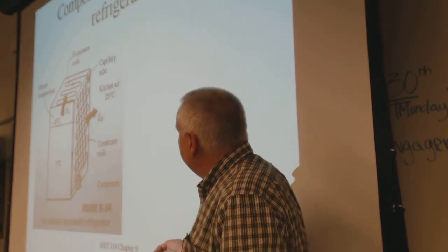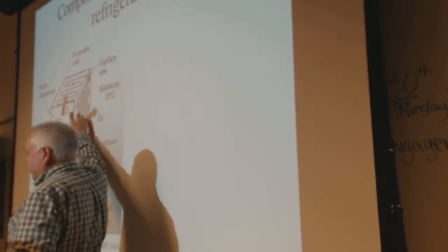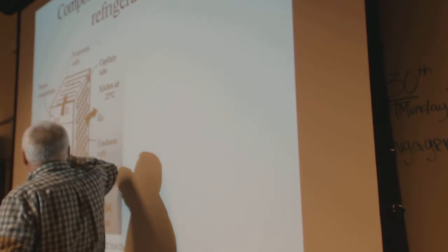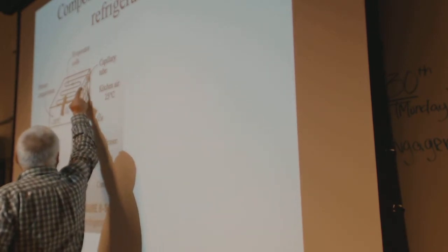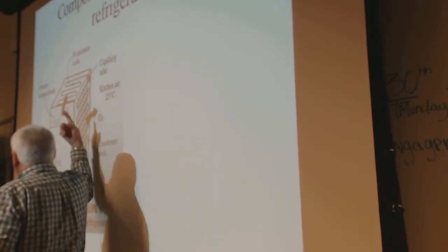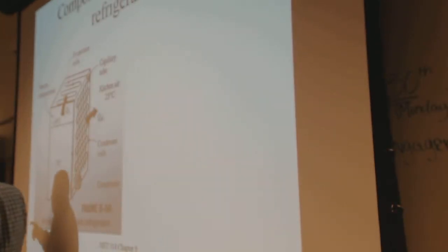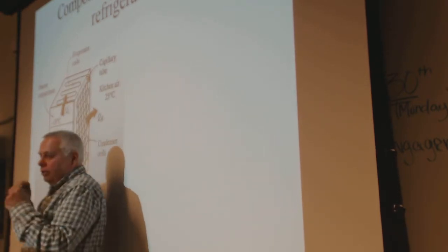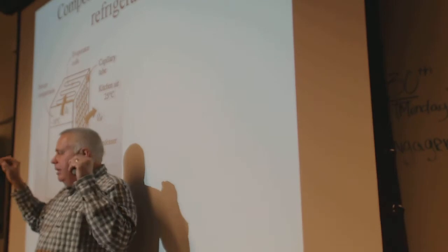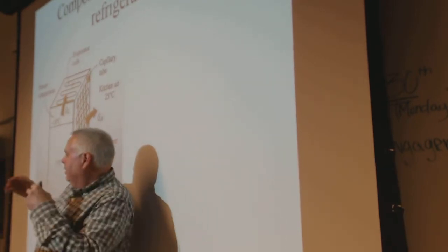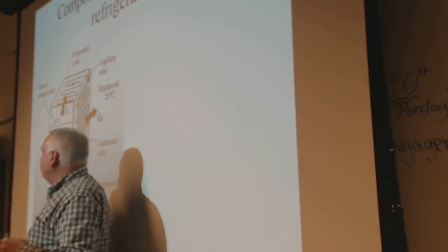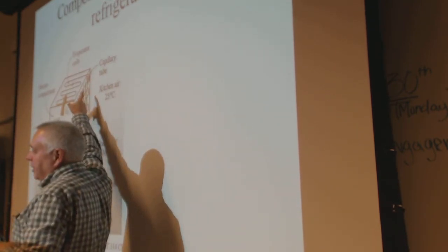So here are some of the components. The back of your refrigerator is going to have stuff that gets hot. That's the condenser at high pressure. It comes off of that as a liquid, goes into an expansion valve. In this case, it's an actual expansion valve. Some of the cheap, like beer fridge kind of refrigerators, they literally just put a long tube that's really tiny, and depending on how long you make it, it will hold back the pressure, and it's just a fluid restriction. That's really all you need to do.